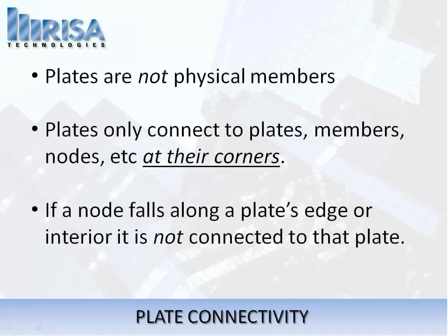Now, the first thing to point out relates to plate connectivity. And what I would like you to know is that plates are not physical members. When I refer to physical members, what I'm talking about is how members operate in RISA-3D. We have what's called a physical member. With the physical member, that means that if you drop a node in anywhere along the length of a member, the member automatically connects to it.